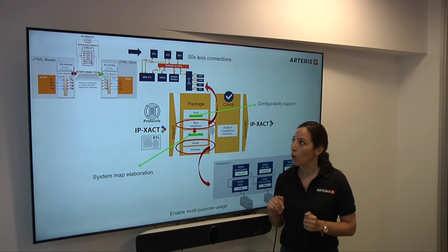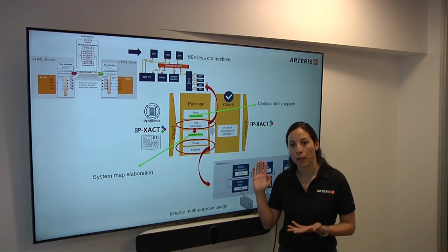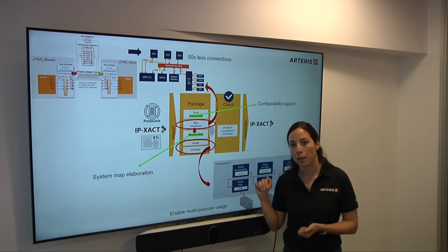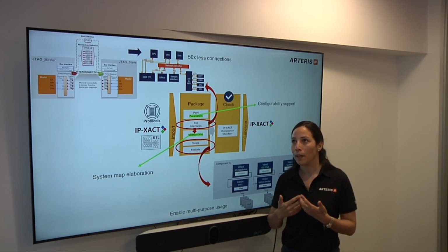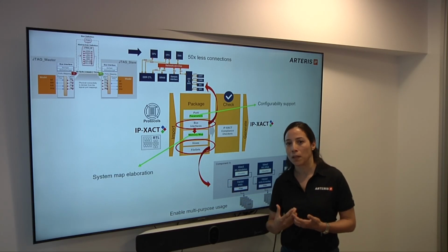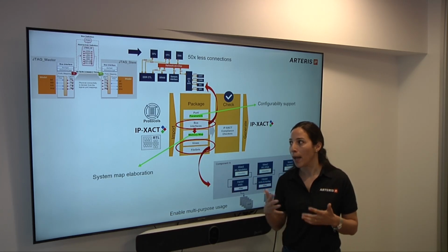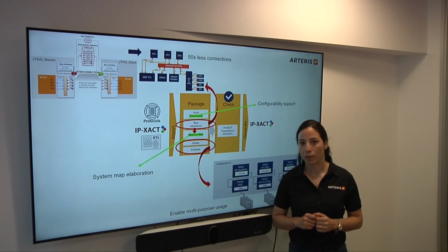And also, with the new IP-XACT version that we are supporting with this new product, it's much easier to address the SystemVerilog specific features like the structs and the SystemVerilog interfaces. All these are now natively supported by the new version of the standard, and it will help to streamline the integration process. How has IP-XACT evolved to make all this work?